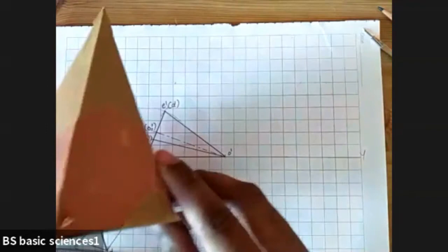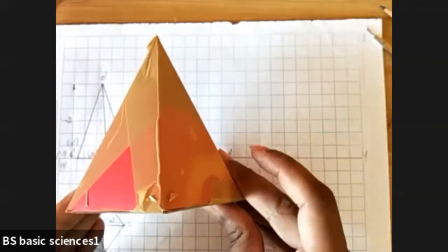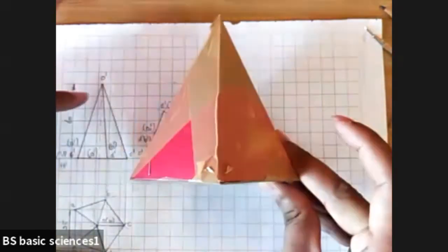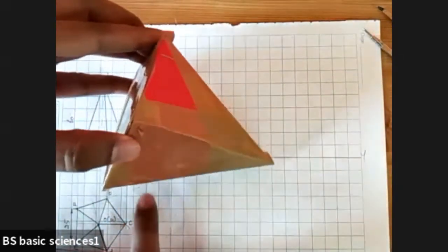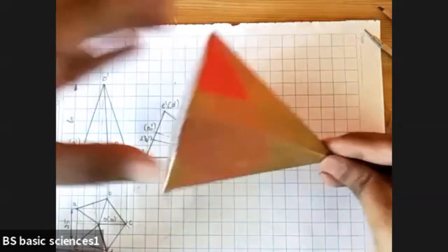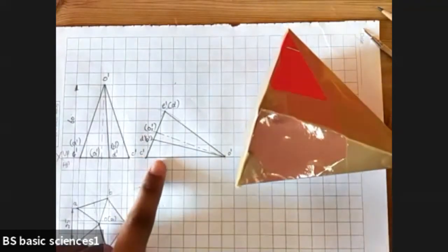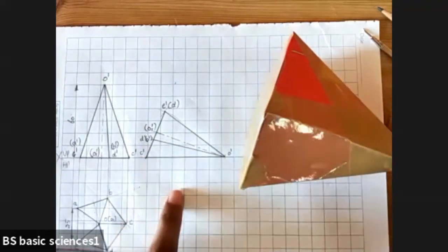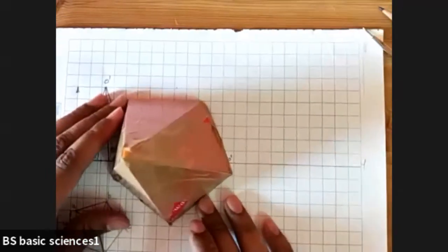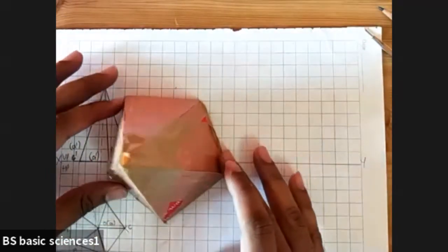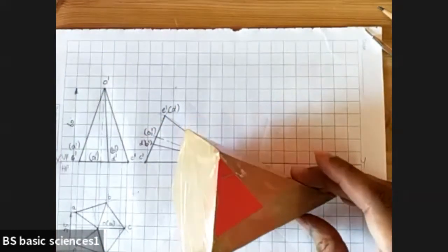The pyramid was placed with respect to one of the edges. In the front view, you can see these three, which is what we have drawn here. Then what he has told us is to incline it with respect to another slant edge. After inclining like this, this is the sketch we have drawn here. Now what will happen to the top view? In the first condition it was like this. In the second condition, you have inclined it with respect to one of the slant edges. Now this is your top view.